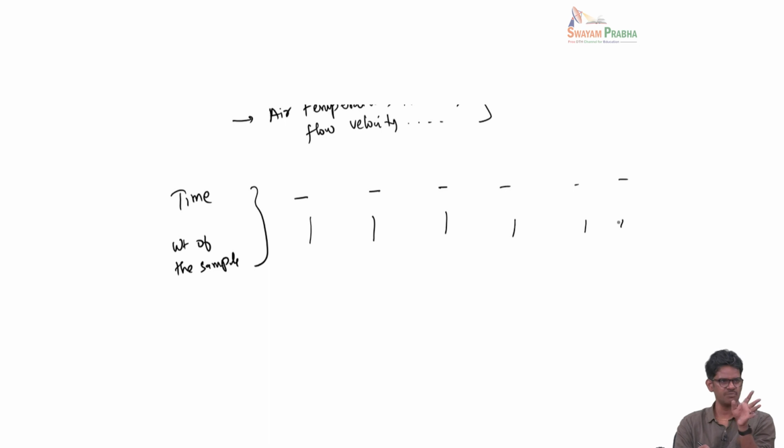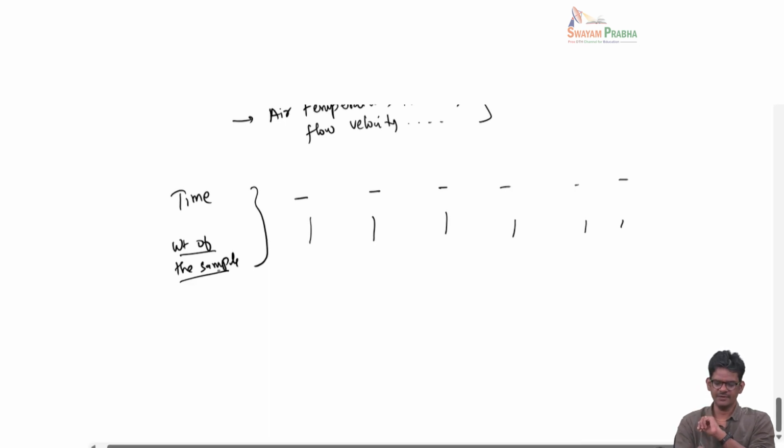And let's say you also know what is the dry mass of the solid. Okay, in the absence of any moisture, you can get that by putting the sample in a furnace and heating to a very high temperature, also making sure that the material does not decompose. So when you do that, pretty much all the moisture will be gone. Okay, and then you take that as a dry mass or bone weight. Okay, bone, it's called bone dry solid without any moisture. You get that dry solid mass, and when you take the difference between this weight of the sample and the dry weight, that will tell you how much amount of water is present in this material.